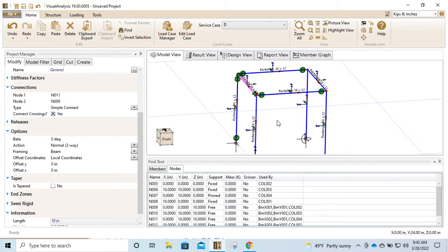But as Adam said, if your model gets very, very large, it's doing a lot of operations to get to that stiffness matrix. And based on the fact that we have to truncate at 16 decimals, right? There's the ability to have a very, very small value. It could be 0.000001, and that gives it enough stiffness to where it would run. But then the next time it might not run, right? And it might not give you the results that you want.